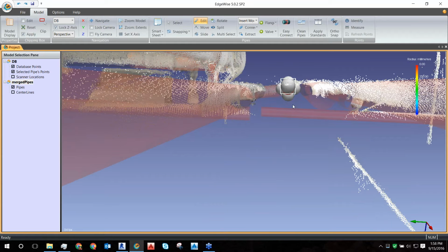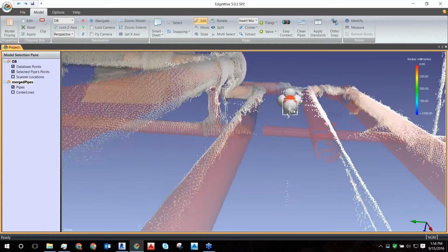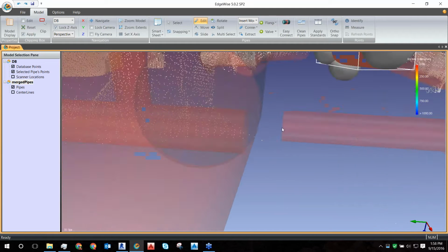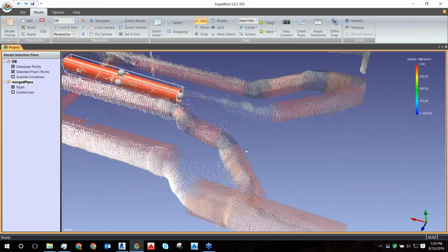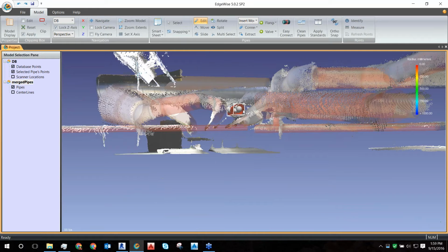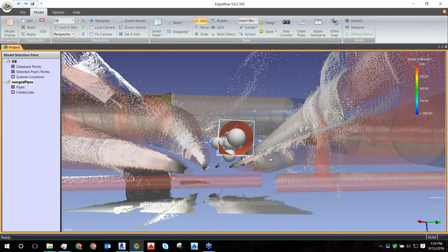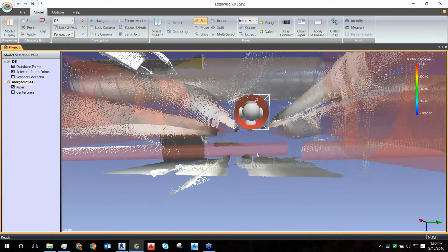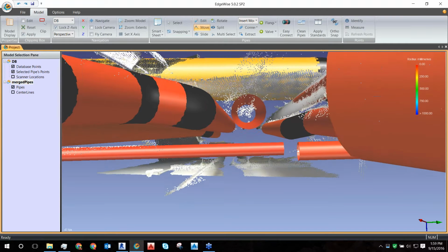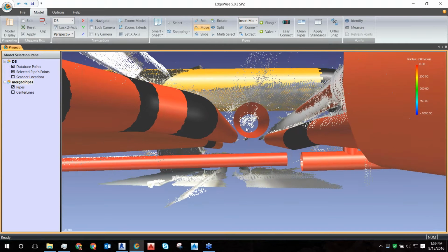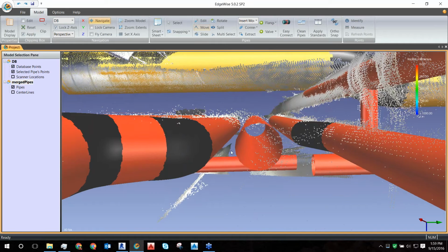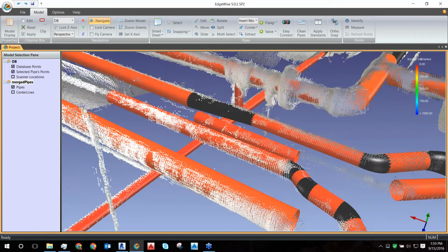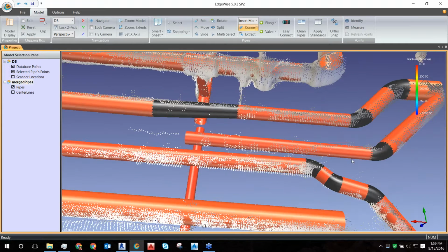Another sophisticated workflow is to do it in the office with applications like Cyclone from Leica or RealWorks, where we can combine the terrestrial data with the handheld data. So we capture the big areas with the terrestrial scanner and fill in the shadowed, occluded, missing areas with the handheld data. That's a well-established workflow, and we have a number of customers running with that. Yeah, absolutely. I know a number of people trying to do exactly that, using that exact workflow. That's a great point.